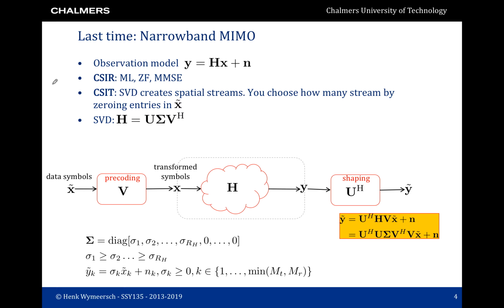When the receiver has an estimate of the channel H, it can perform different detectors, such as maximum likelihood, zero forcing, or MMSE. Maximum likelihood is the optimal detector. It requires searching over all possible X values that could have been transmitted and is thus exponential in the number of transmit antennas. Zero forcing tries to invert the channel. However, this fails when the channel is poorly conditioned, as the inversion leads to noise enhancement. Finally, MMSE tries to approximately invert the channel and thus reduce noise enhancement.